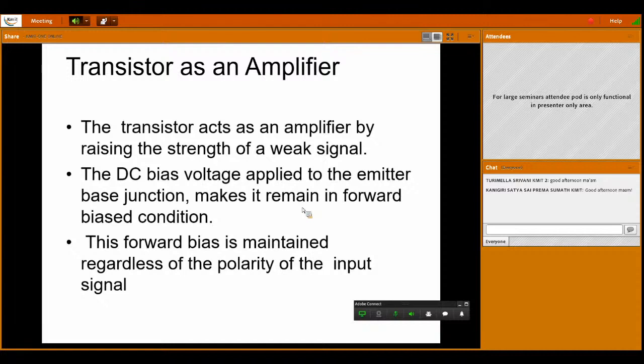These amplifiers consist of a transistor operated in the active region, which can amplify the weakest signal. Hence it is named a small signal amplifier. It is desired that the amplifier be operated in the linear region, so that our output collector current will vary with the input base current IB.